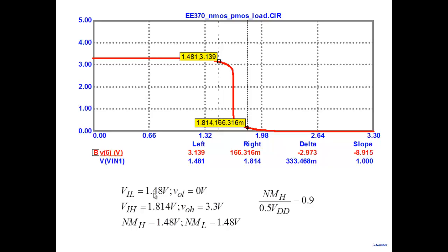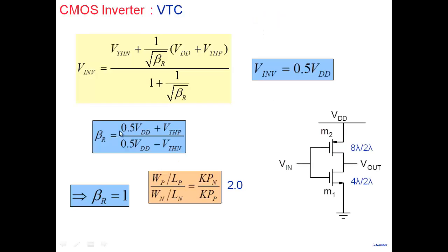Right? 1.68. You want to shift it by 0.2 volt. So change your inverter threshold voltage by 0.2, approximately, because the shape of the curve doesn't change that much. The shape of the curve will not change that much, so shift it right by 0.2. So instead of the inverter threshold voltage of 1.65, which we designed here, if you go back, we took this as 1.65. And if you want to shift it by 0.2, maybe make it 1.85.